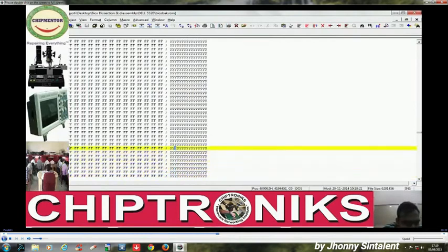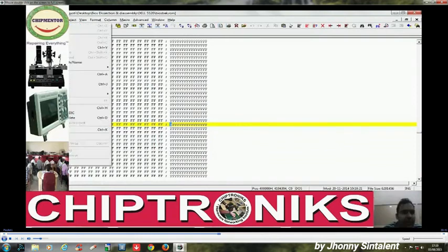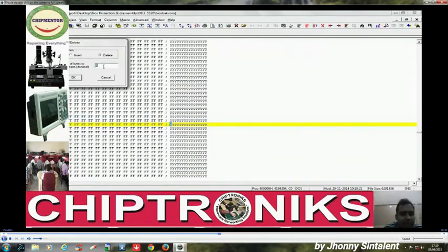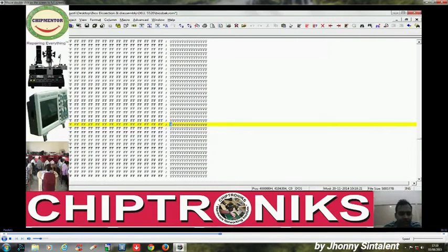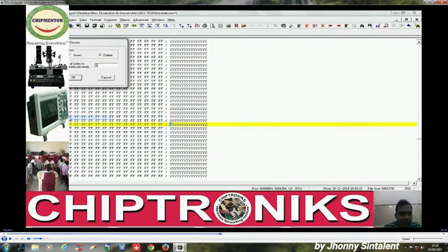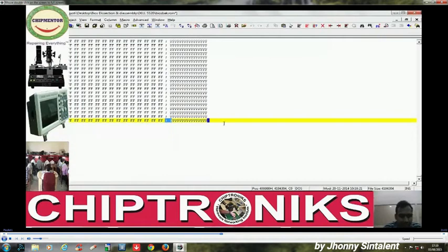So we have to follow very smoothly, no error. Yes, we'll put our cursor over here, and the data above this address is system BIOS, so we'll delete the remaining data. You go over here, hex insert delete, put values as much as it deletes. Still not deleted the remaining, so we'll select again, we'll find 1356 unit 9. All right, so all the data is deleted after that.